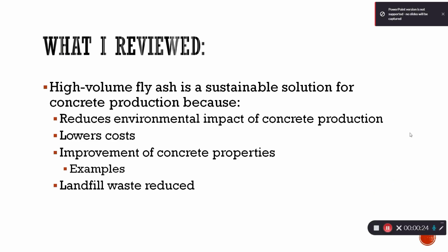What I reviewed along the way was high-volume fly ash as a sustainable solution for concrete production because the addition of fly ash in concrete mixtures reduces environmental impact of concrete production. The addition of fly ash in concrete mixtures lowers costs. The addition of fly ash in concrete mixtures has the ability to improve concrete properties in fresh and hardened concrete. I have 3 examples from journal articles to support the improvement in concrete properties with fly ash added as a replacement to cement. The addition of fly ash in concrete mixtures also reduces landfill waste.